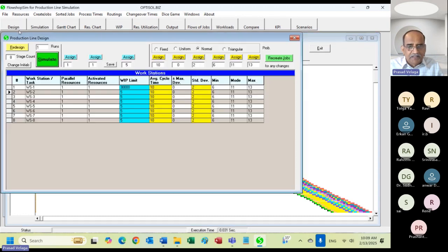Okay, now what I will do, I will take the deterministic case again, but an unbalanced scenario. I'm considering different scenarios now. So let me, for example, set the cycle time to 24. Here only 7. There is a 32, and say 15 here, and 36 cycle time, pretty large, and 10. And because the 24 is pretty high, I will put two machines here to reduce the unbalancedness. Two machines here and three machines here.